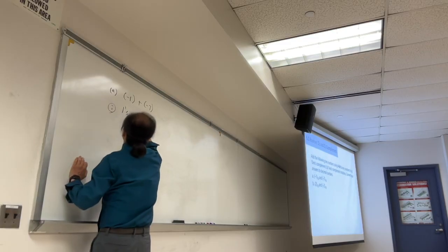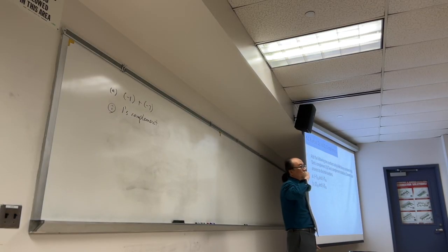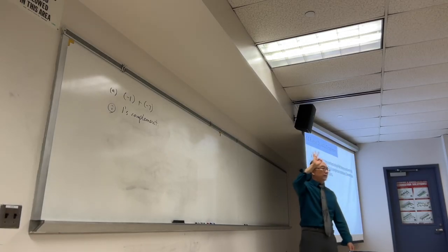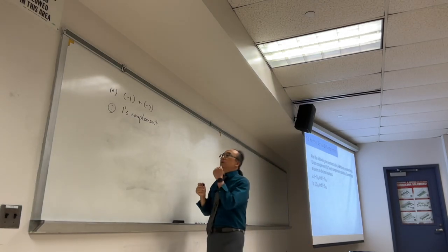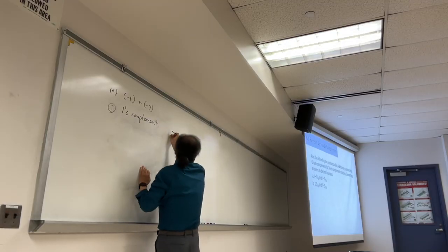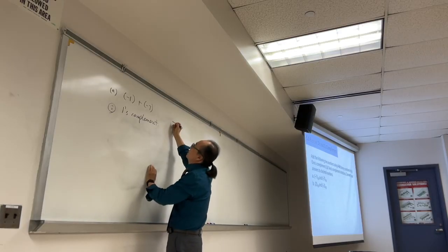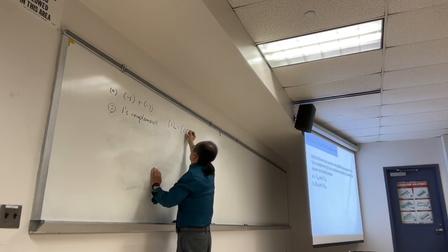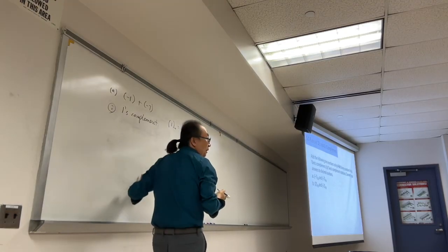Using 1's complement. Finding negative numbers, I don't know in your 312, probably you talked about 3 different ways to put it in the negative numbers, but in our class in 145, only 2, 1's complement and 2's complement. So to get to negative number, we need to work on positive first and then turn that into 1's complement or 2's complement. So positive 1 is 0, 0, 0, 1, because it's a 4-bit number.